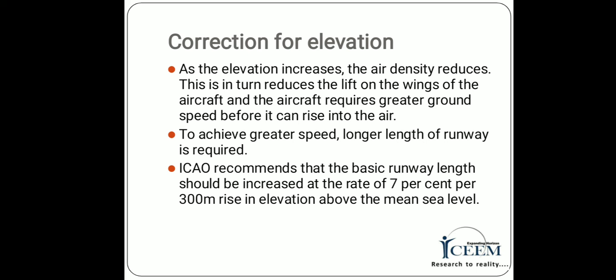To achieve greater speed, a longer length of runway is required. And last, ICAO recommends that the basic runway length should be increased at the rate of 7% per 300 meter rise in elevation above the mean sea level.